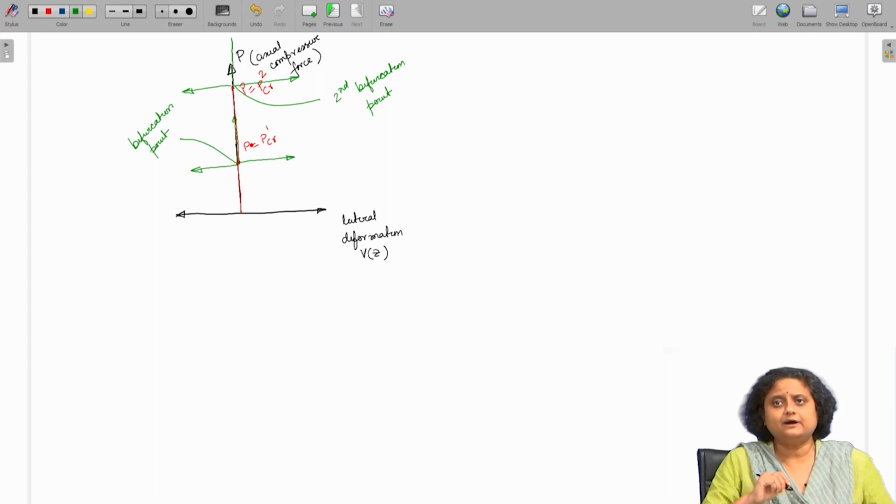And then if we further increase the load, if it deforms, then it will just fail or not fail. There is this instability, it is most likely going to fail. But if it does not deform, then we can further increase the load and go to the second critical value, P critical 2, where again a bifurcation point happens.